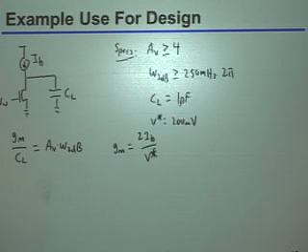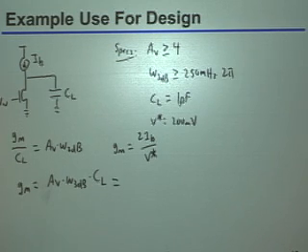Okay? So if I combine those two things together, if I push CL over to the side, I can say that GM is equal to AV times the 3 dB bandwidth times the load capacitance, and that's also equal to 2 times the bias current divided by V star.